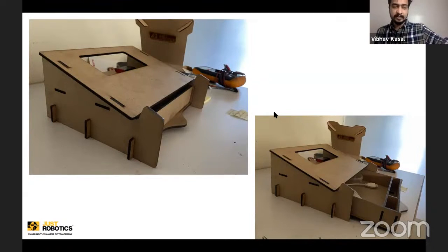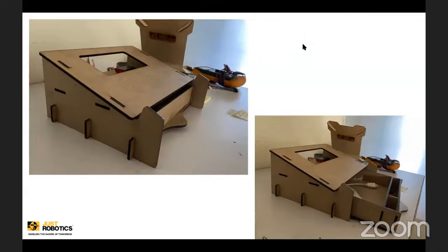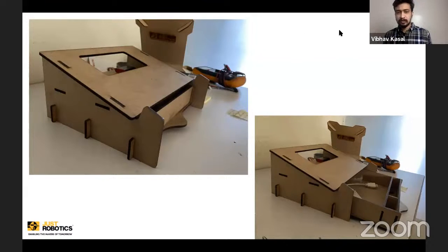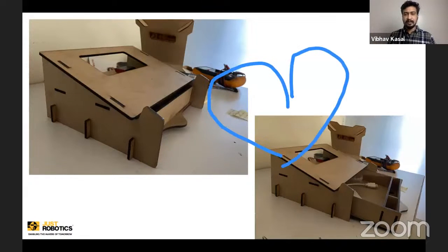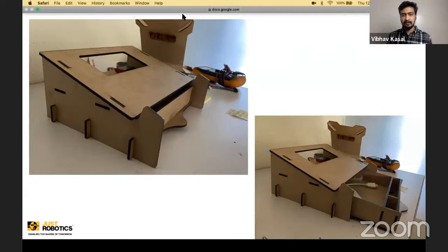Usually the people who have a laser cutter have the experience to know the speed and the optimum setting even if you just give them the material. Just that they will slow it down intentionally so that they can bill you more. So you can ask them to increase the speed a little bit more and see how the cut is. It becomes a little iterative process. But if you are getting just one thing cut, then you don't have any problem.